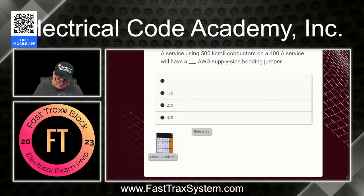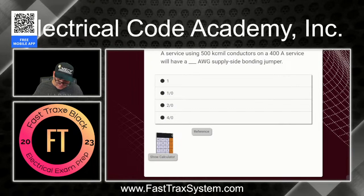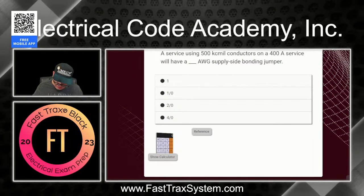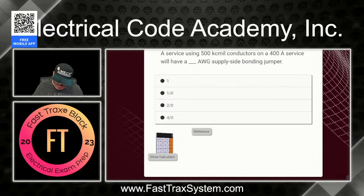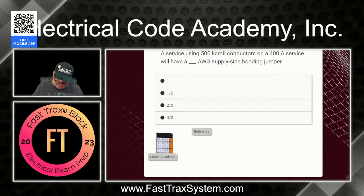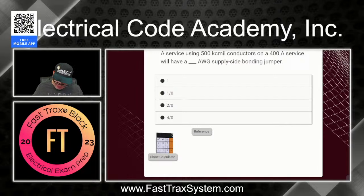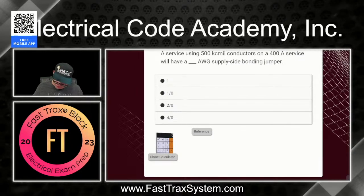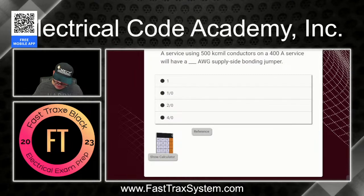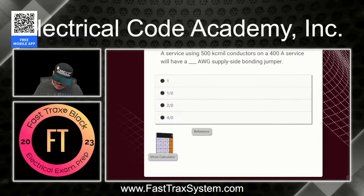So I'm looking down. Let's see here. Equipment, no. Okay, service equipment. The question was about service equipment. And it says, okay, since we're under bonding jumpers and it says service equipment, it's 250.28. That's going to talk about main bonding jumpers. We see 250.92(B). It says bonding component. And we see 250.102(C). That's where we know that we need to be.